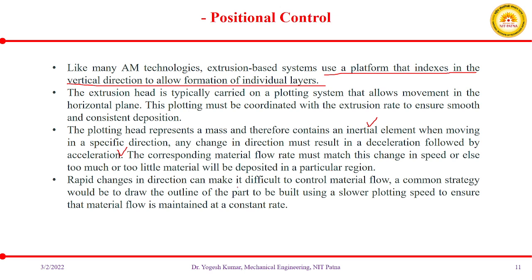Rapid change in direction can make it difficult to control material flow rate. If you are moving your plotter head at a very high speed and trying to change its direction, it will be quite difficult to maintain the flow of your material during these rapid directional changes.